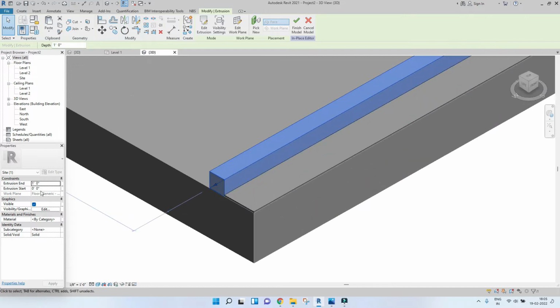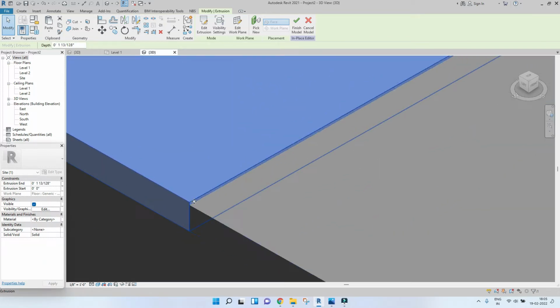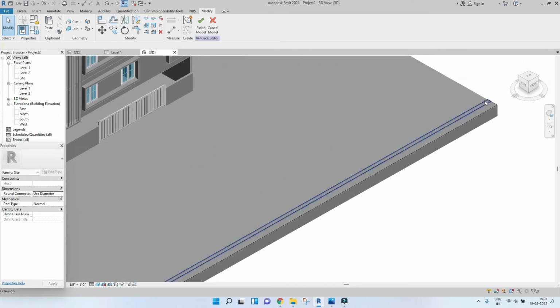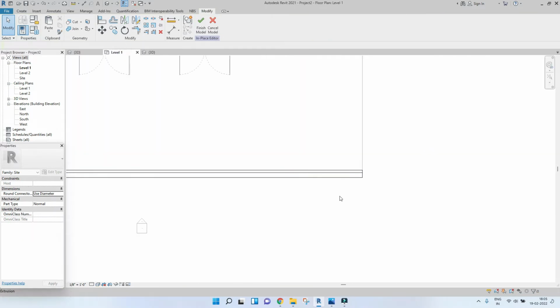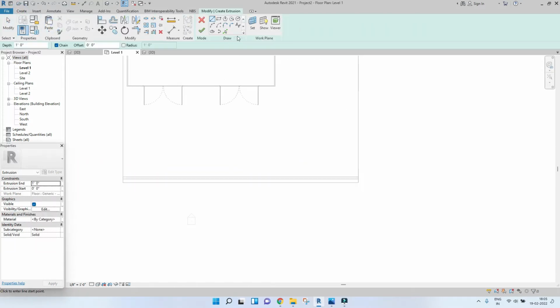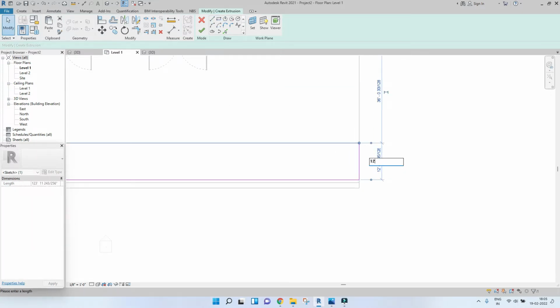So we'll keep the solid line just a little bit higher than the other surfaces, just to make it visibly a little different. And once we're done with the solid line, the next thing will be a roadway, and we'll keep the width of that to 12 feet.